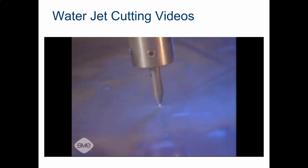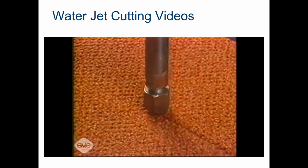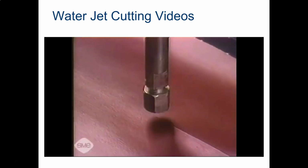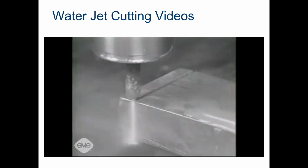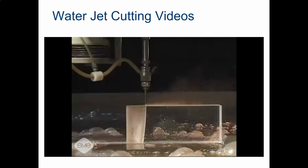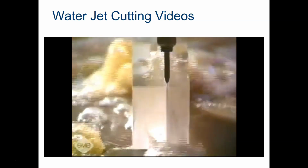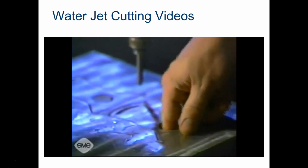Dust is also non-existent. Abrasive water jet systems cut materials that gum up saws or suffer unsatisfactory heat damage in thermal processes. They are good at cutting laminates of different materials, including composite mixtures of metals and nonmetals. Thick materials may also be cut using the abrasive water jet process.